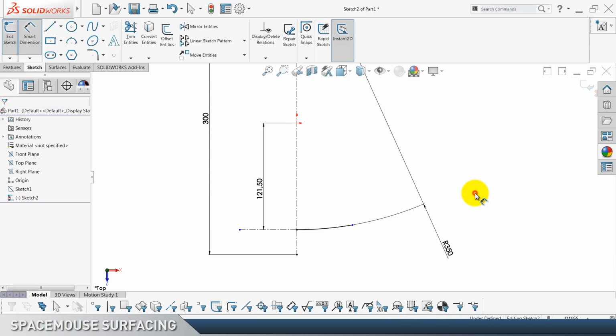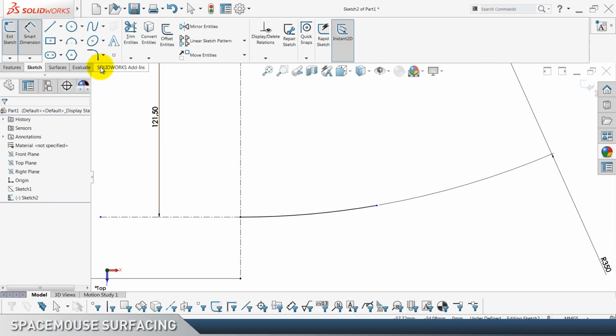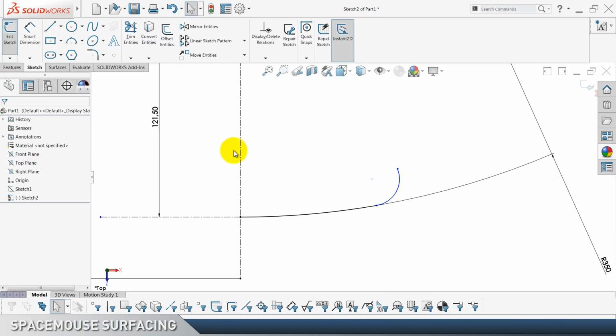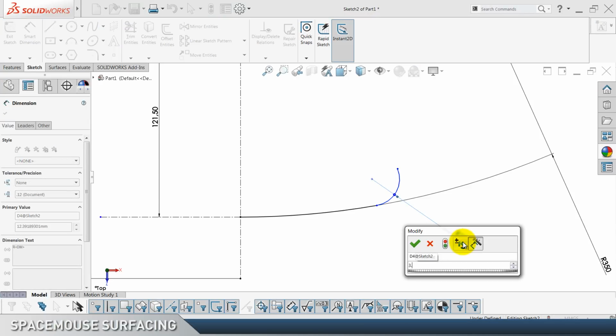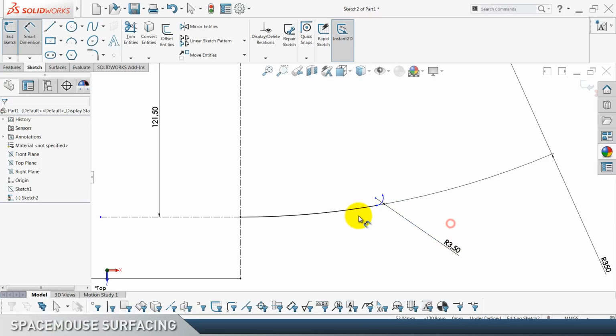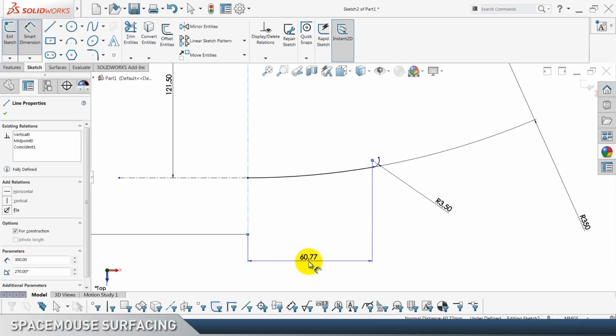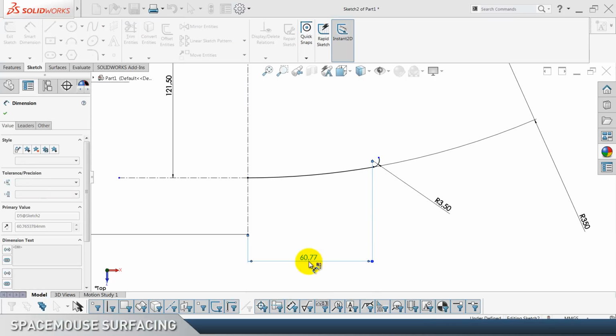And this is gonna be slightly different sketch from the first one. So at the end of this tangent arc we draw another one. It's gonna look something like this, and the radius for this one is 3.5. And now this point goes from here 48.